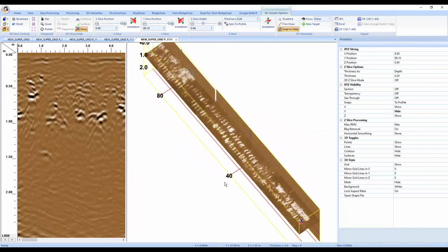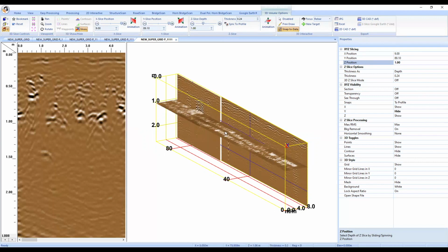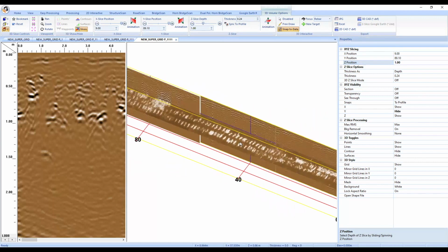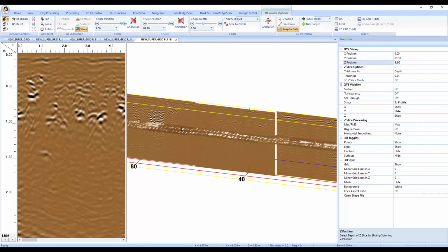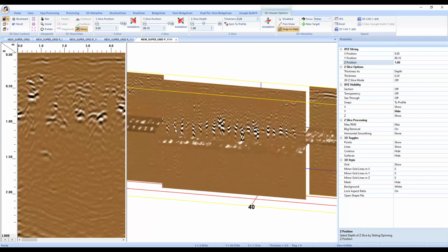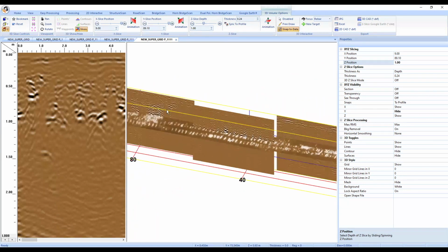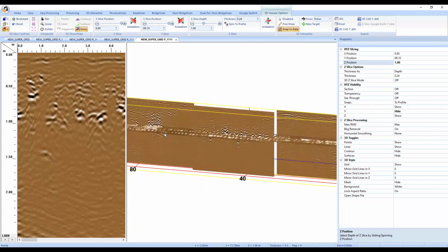And we can see here that our graves appear to be about a meter or so down, which makes sense. You can, of course, type in a number here, not 100, just 1 would be fine. And that also brings everything to the right depth. I can pull my profiles in to confirm that. And you can see here that our grave shafts are right over here. There are these lines that we can see. Surprisingly clear for data in clay. A wet clay at that.